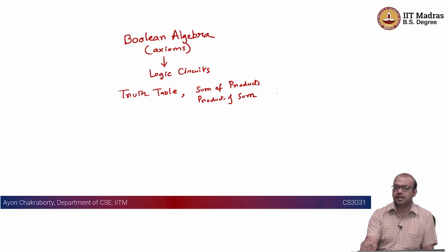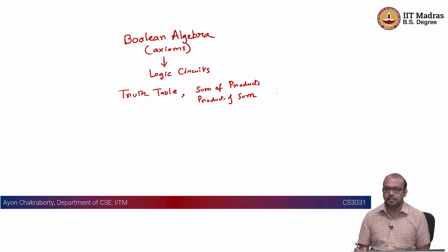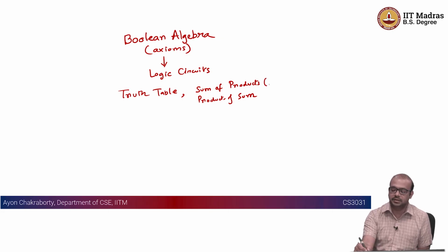These are not optimized in terms of the number of gates. Based on how many outputs are 1 in the truth table, those are going to be the min terms for your SOP expression, and you can further simplify that. So, this is the SOP expression we have studied, and the POS expression we have studied.